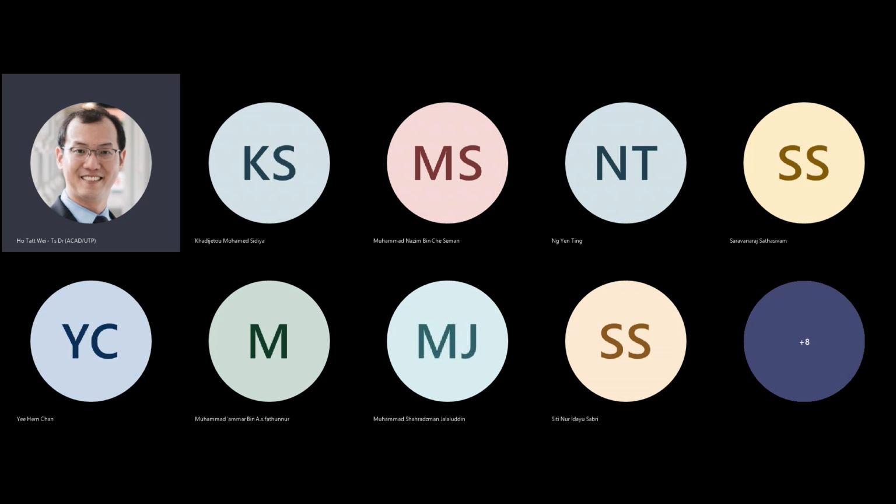Thank you. So just recapping, one of the first competencies for you to develop will be to understand how you can assemble digital logic gates using complementary metal oxide semiconductor. You think about them as switch networks, a pair of complementary switches. One is an NMOS transistor, one is a PMOS transistor. How do you assemble them in various configurations like the multiplexer, the NAND gate, NOR gate, NOT gate? And just how do you start to think about them?